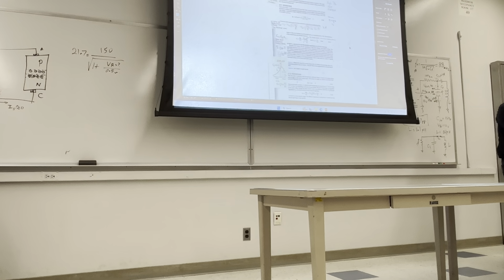When the crystal vase is empty and you bang it, bing, it goes oscillating for a long time. That phenomenon is called resonance. The longer, the better. So in order to have a high Q LC circuit, a well resonant circuit, you've got to have a minimum amount of losses. 100K is typical, it's a very low loss. So what purpose is this serving?